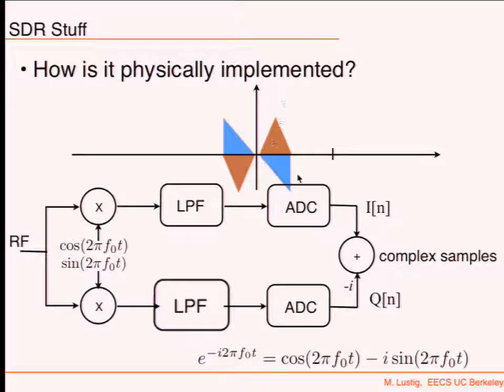When you do this, there could obviously be some issues. First of all, if the two channels here have some discrepancy between them, let's say there's a bias in this one, or the gain is different in each one of them, then the cancellation of the negative part and the positive part will not be correct. And then you'll get what's called an image. I don't know if you heard the terminology image rejection, but when people design IC circuits for RF, there's this thing called image rejection. How good is your ability to get those two together and get the good gain?